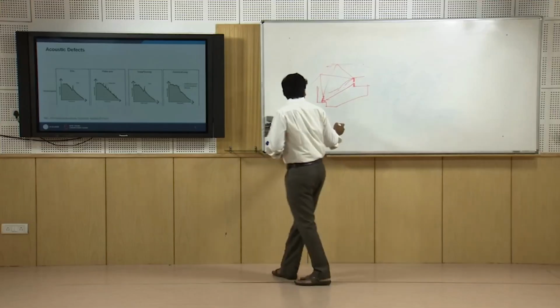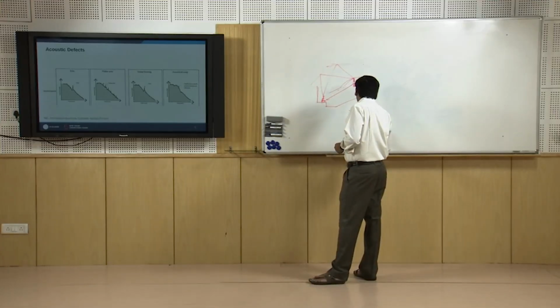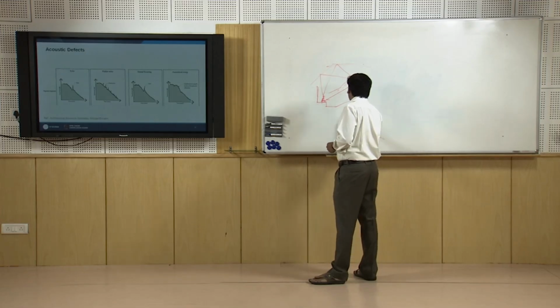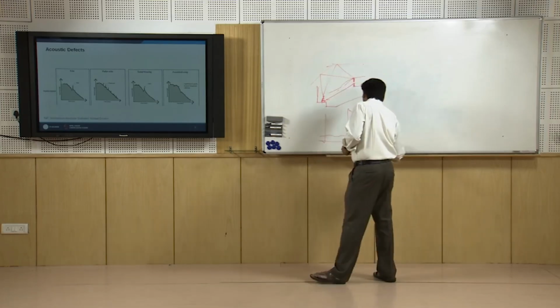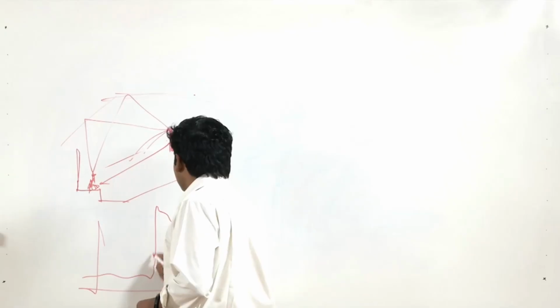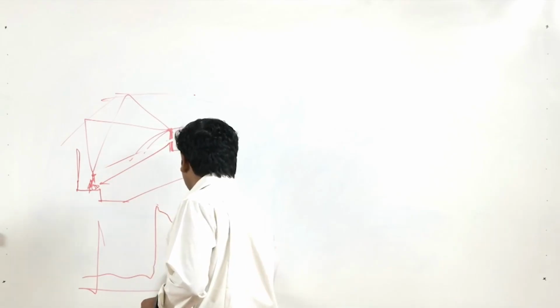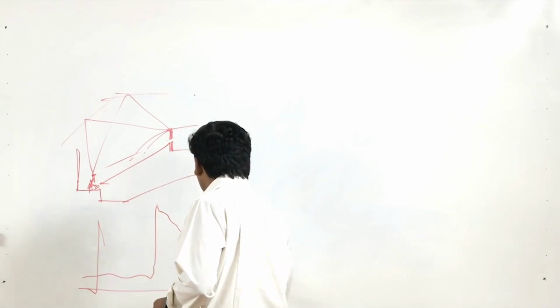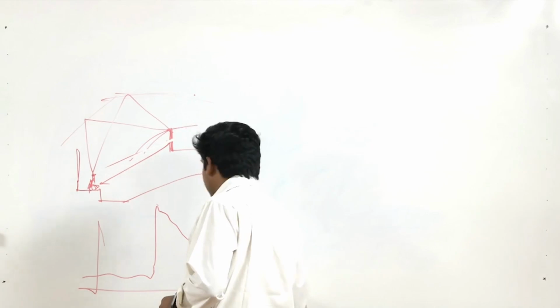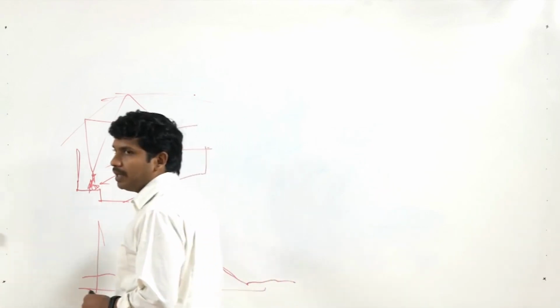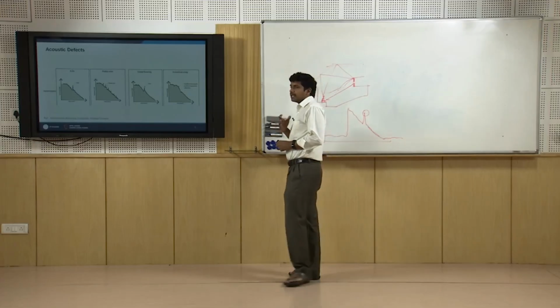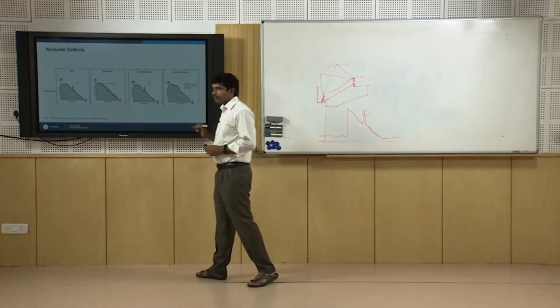You had a gradual decay of sound, then another sharp impulse, then it decays down. This was your original sound and background noise level; you made this impulse, it decayed down, you find a sharp rise, then it further decays, which means you have a problem of echo. You will be able to find it if you record the reverberation time carefully.